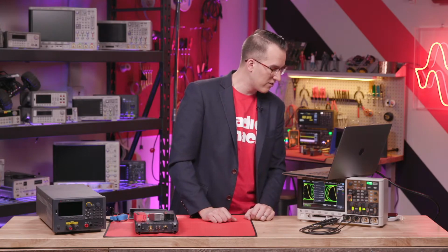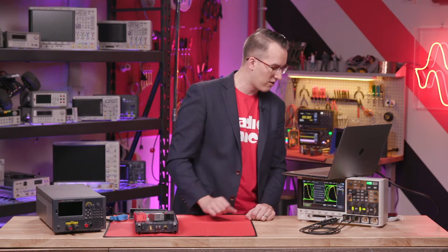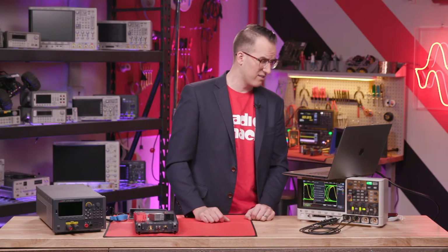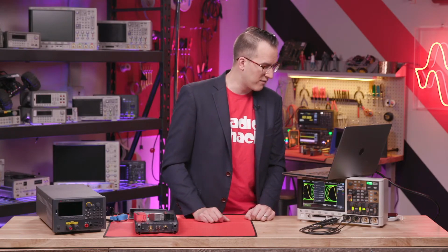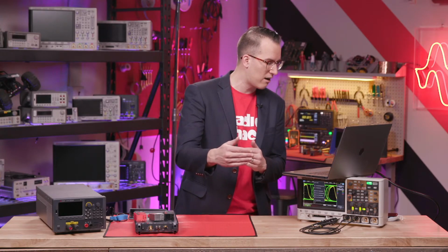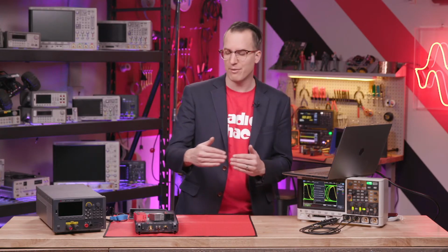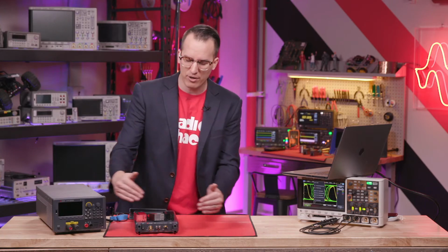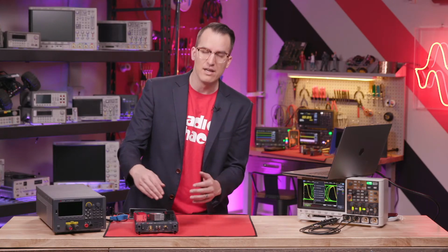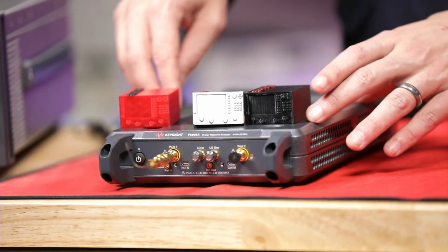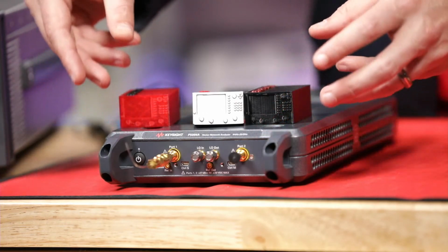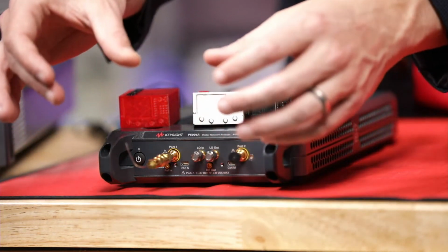Lots of questions about calibration. So someone's referencing calibration kits. Joel says, if you add probes or fixtures after the cal plane, the calibration plane is basically you calibrate, and I mentioned it briefly in the video, you want to calibrate your VNA not just for your outputs, but for your whole measurement system up to your device under test.